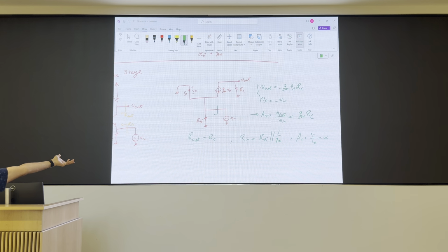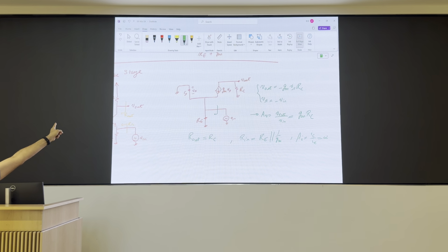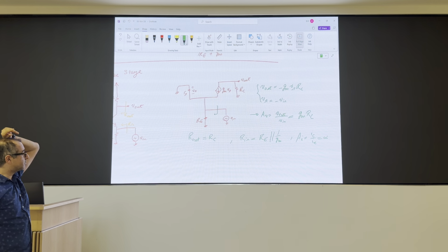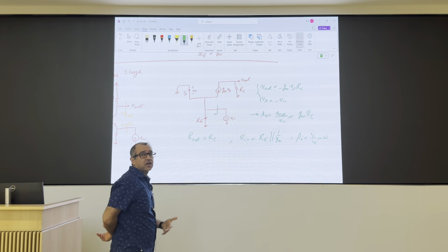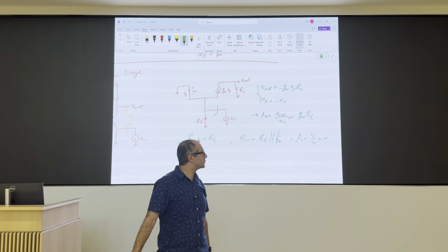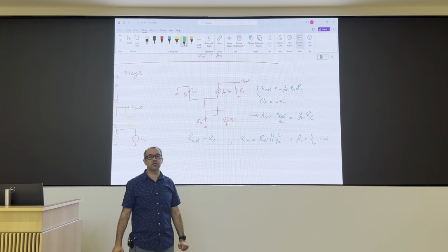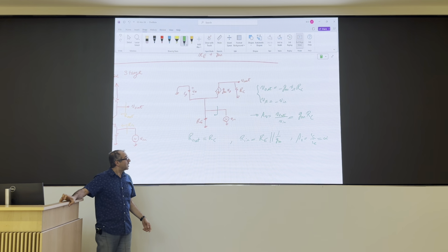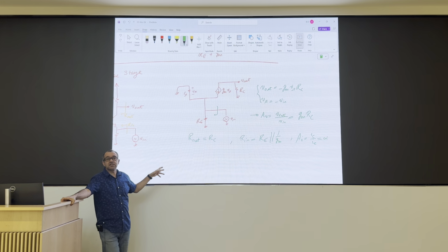If instead of this, you make a common emitter stage, you can get the same gain, a high input resistance, and a current gain as well. And the output resistance is the same for both anyway. Does it have something to do with power? Because if the power is the same, just the voltage is higher and the current is lower? No, same thing with common emitter. True, but we don't really have much use for those. We don't cover it in this course.